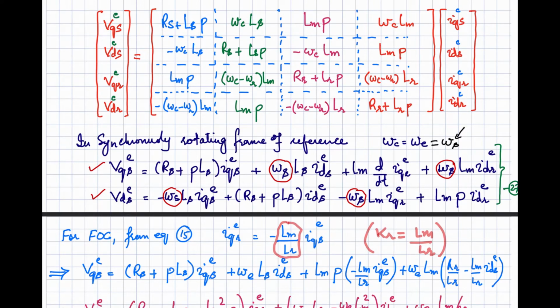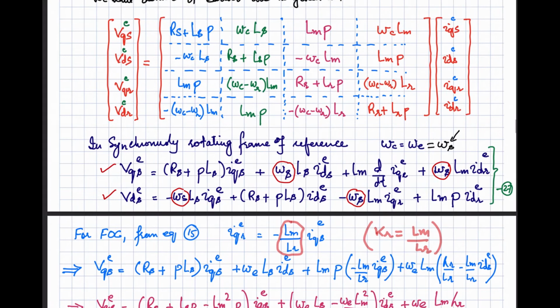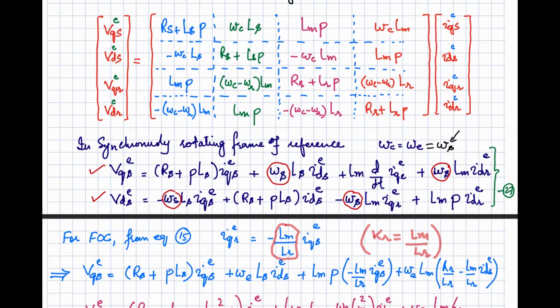current, because in squirrel cage induction machines it is difficult to measure the rotor current, since you do not have access to the rotor winding. Only in the wound rotor type machine do you have access to the rotor, but that is not used extensively in the industry because of the carbon brushes and slip rings involved at the rotor side.